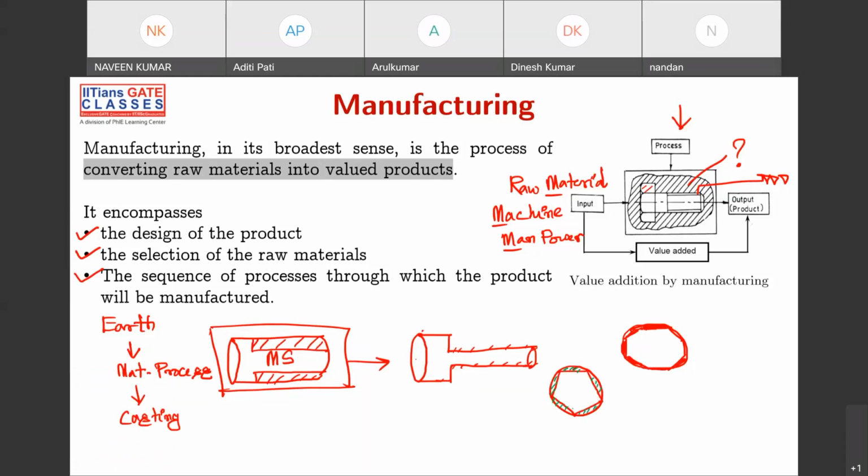Okay, so see, there is a series of processes. Casting, right? Then what did you do? Turning, right? Then you did threading. Then you did some milling, chamfering, whatever it is. Then the bolt is ready. You can't change this order. Maybe some orders can be changed, but you can't go directly to threading before turning, obviously. You can't directly go to milling before turning. It's difficult, right? So you have a series of procedures that you're going to do.